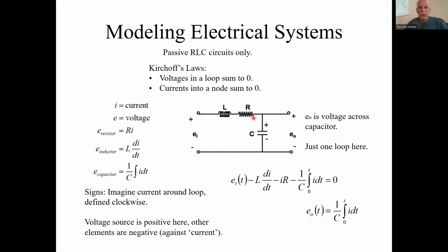And each of these elements has some kind of voltage drop. This is an external forcing function like a battery. You have to be given what's positive for this force. So it's labeled as plus up here and minus down there. The voltage drop across these passive elements is opposite of the current through them.